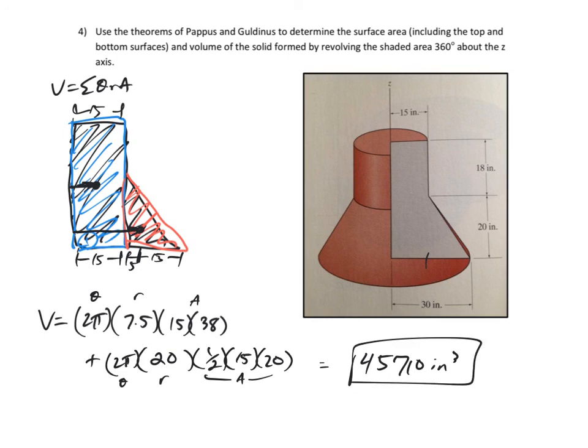All right. So make sure you're ready for surface area and the volume for those theorems of Pappus and Guldinus. I think it's straightforward. Just make sure on that sheet, whether you're looking at the centroid of a line or centroid of an area. One other thing, don't forget that the weight is the specific weight times the volume. In case I asked for the weight instead of the volume, you could have found the weight for that problem as well. All right, good luck.